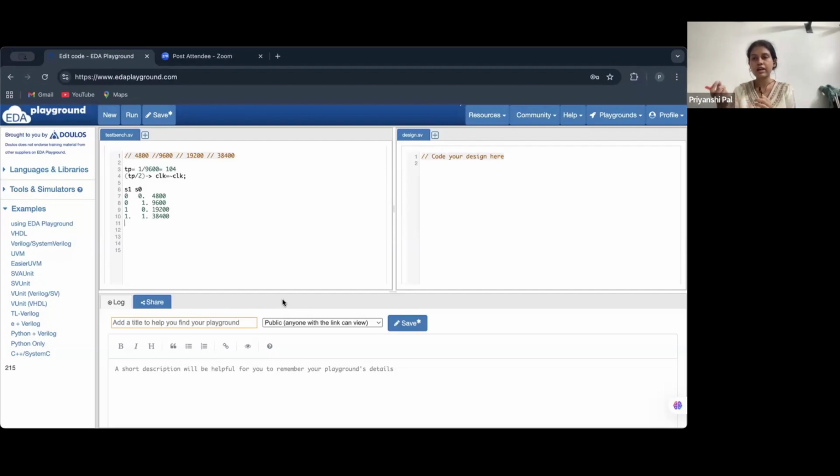If this address is invalid, it will send acknowledgement as 0. Let's suppose that it was the valid address. Then the master will receive the acknowledgement, and it will send the register address which is inside the slave. For that also the slave will send the acknowledgement or not.